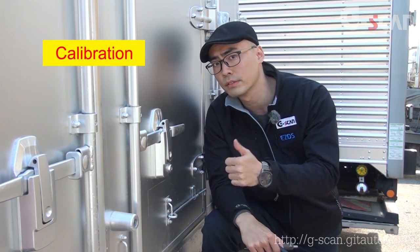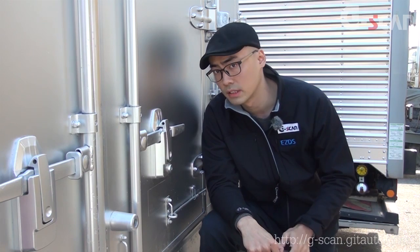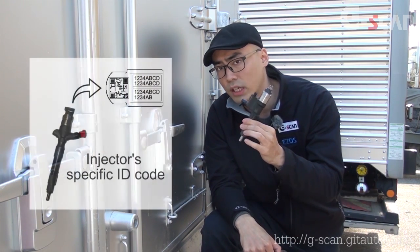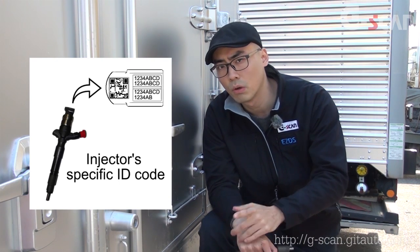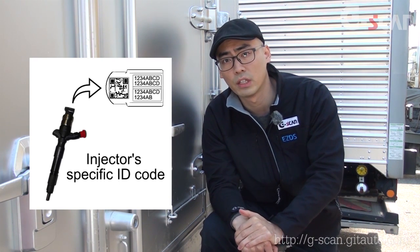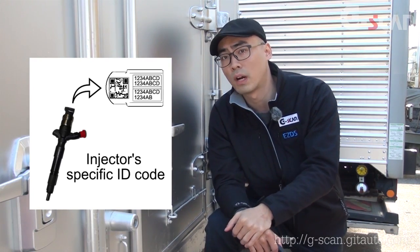Other than erasing and learning function, there's calibration, initialization, reset, and coding functions. One out of many different examples will be injectors. When you replace injectors, you have to code or write specific injector's ID code into ECU for correct fuel quantity adjustment. Let me summarize some key points.